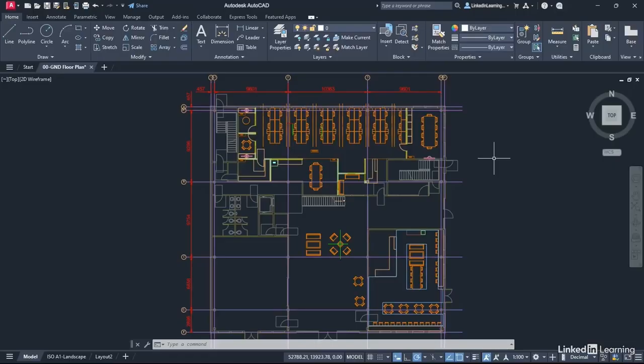So you can see going across the top there, we've got 9601 millimeters, 10363 millimeters and 9601 again between the grid lines. Now, if I go and measure anything such as a door opening, that would also be in context with those dimensions between the grids. Also, it's a good bit of CAD practice. Whenever you get a drawing from somebody else, go and measure a distance on that drawing in the model tab so that you know what units you're working in.